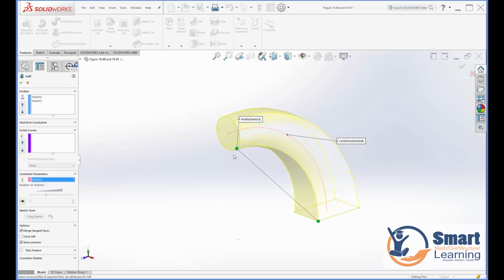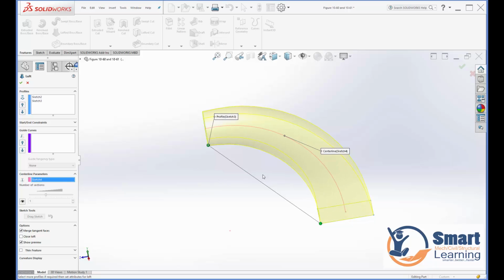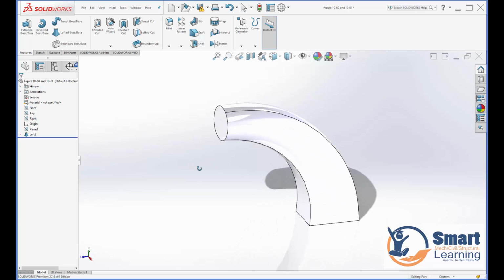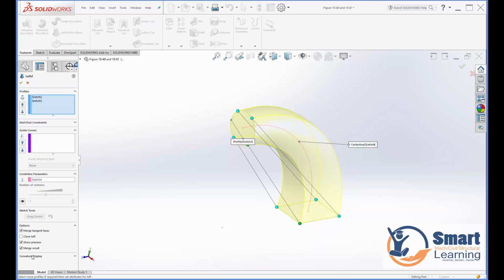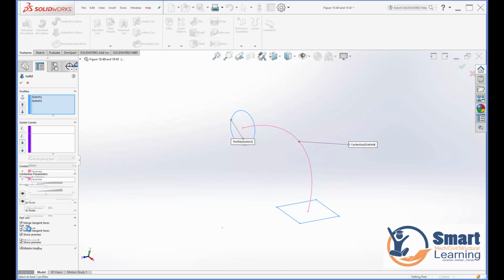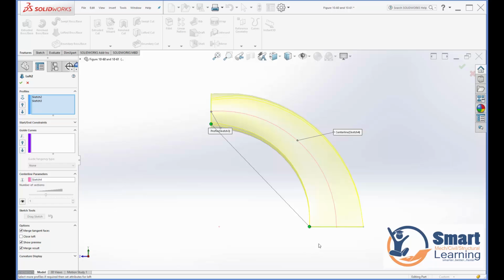And here you can see the green dots where you can switch also for twisting related discontinuity. So this is center line parameter. You have to use this. If you try using this guide curve, you will never get the solution. So be careful. Again, here what you can do is go to edit and go for the other operations like close loft. Here you can see this is not applicable because if you move this particular end, it is not in continuity, there is no tangency here.